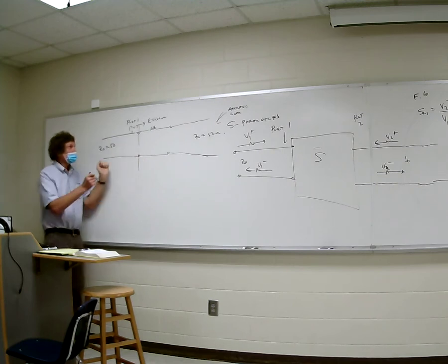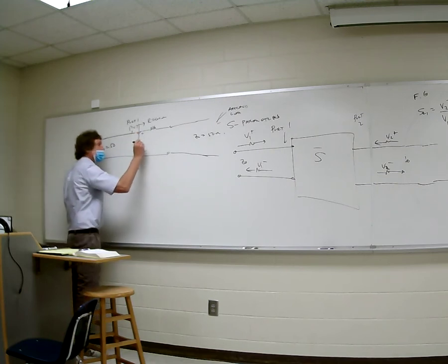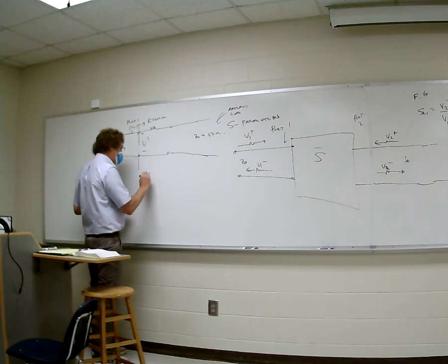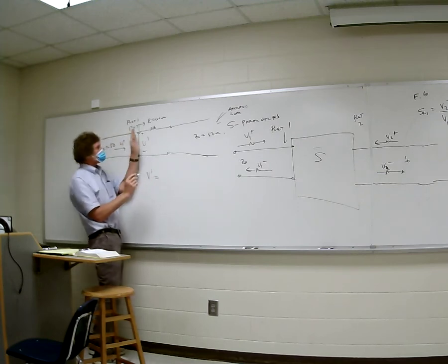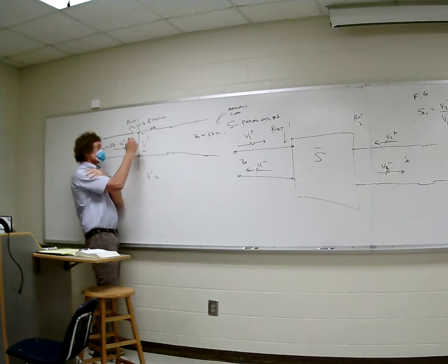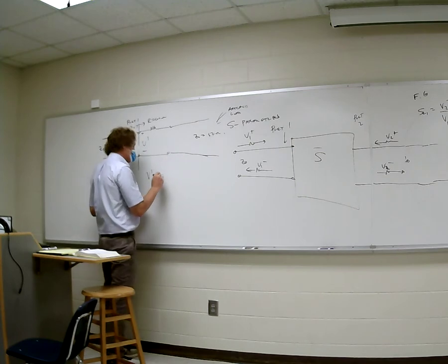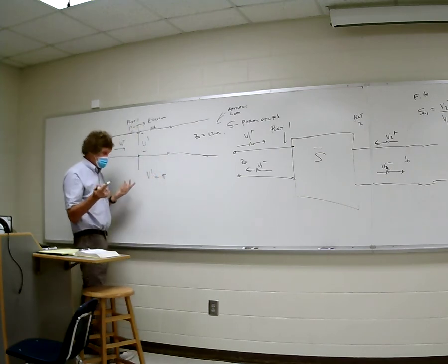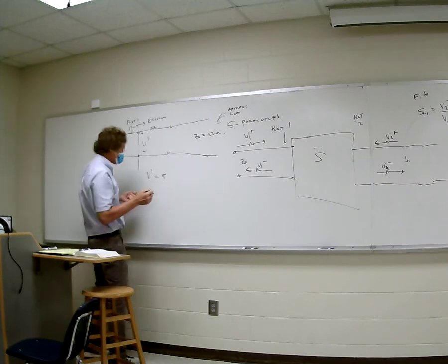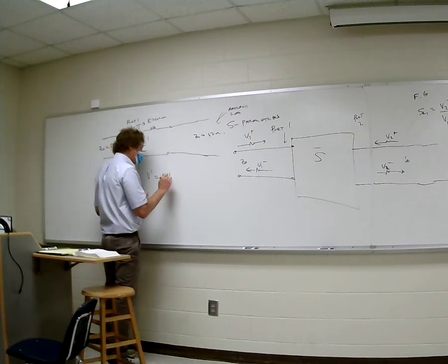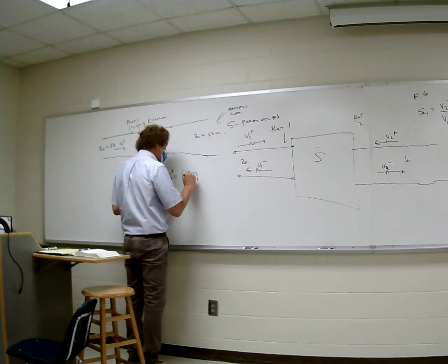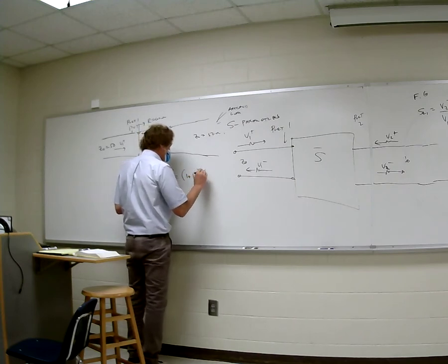So the voltage right here, I'm going to call it V prime. We're taking a look at a wave propagating this way. V prime, that's the voltage just on the other side of this transmission line, would be equal to the transmission coefficient, tau, 1 plus the reflection coefficient, times V1 plus, or it'd be 1 plus the reflection coefficient of port 1 times V1 plus.